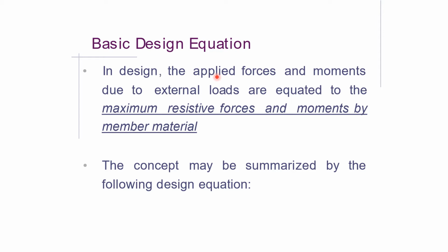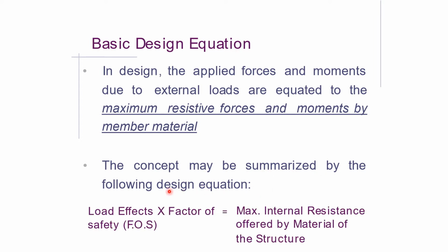In design, the applied forces and moments due to external loads are equated to the maximum resistive forces and moments offered by the member material. Means we equate the applied loading with the material strength. The concept may be summarized by the following design equation. Here, the load effects are multiplied with the factor of safety, and it is equated with the maximum internal resistance offered by the material of the structure.